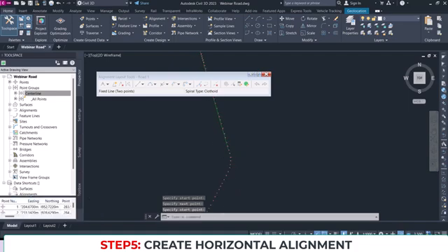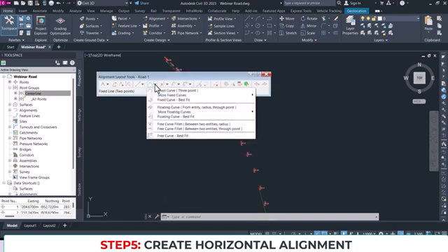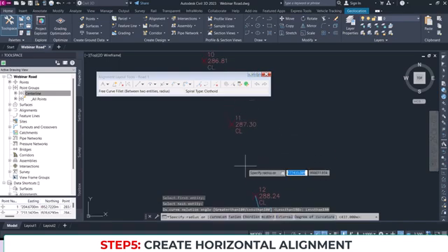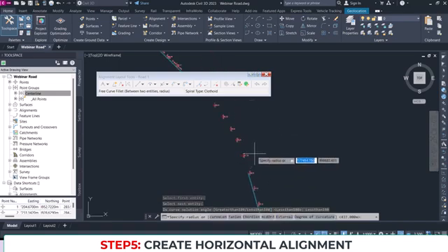Let me just press enter. As you can see, I need to add a curve here, so I can use the fillet command. I can find that here. You open up, you select free curve fillet between two entities with radius. So let's put it here. We select the first alignment and then select the second alignment. The angle is less than 180.